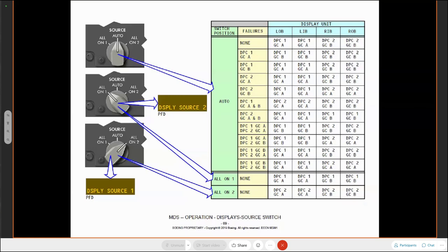There is a page you can go to on the MAX display system. I think there's about 14 pages for the MAX display system on this aircraft, and don't hold me to it, I think it's page 7. It actually shows you as a graphic the layout of the displays and which graphics generator is feeding which display. It's a very handy display to look at, because it's the only real way of seeing which graphics card and graphics generator is connected to which display. It's a handy piece of kit. So that's what this is doing here.